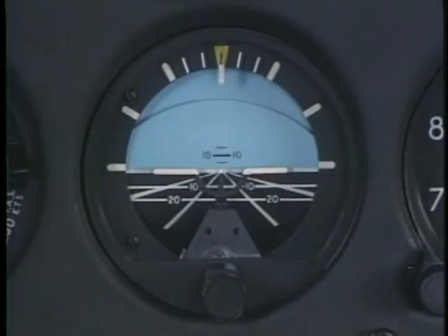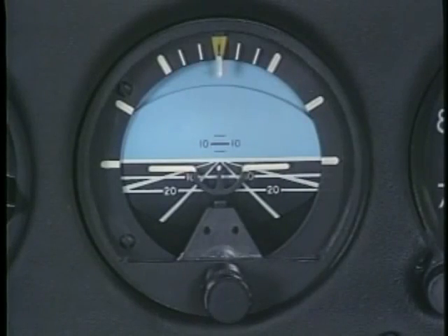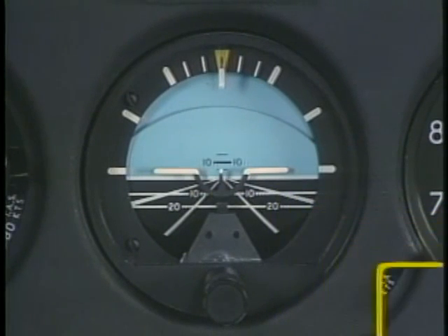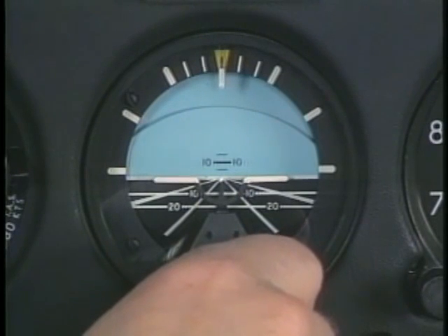In straight and level flight, maintain altitude by establishing the appropriate pitch on the attitude indicator. Normally, the miniature airplane is aligned with the artificial horizon. However, if you increase the airspeed while maintaining level flight, the miniature airplane will be below the horizon. At slower airspeeds, it is above. After you've established level flight for a particular airspeed, you should reset the miniature airplane so it is on the horizon.